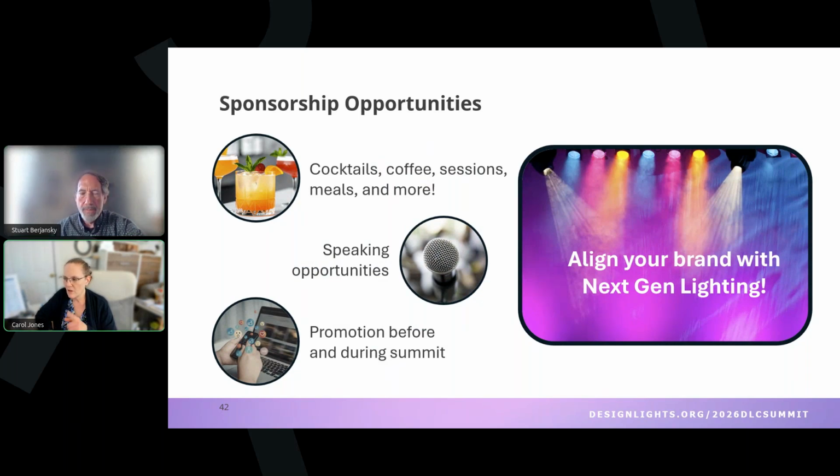Yeah. Another thought that just came up from what you said, Stuart, is that the drivers are all DALI 2 drivers, and there's not much different between D4i and DALI 2. It will depend on things like, are you going to have color? Do you want emergency? Or do you want it to be intraluminaire? When you are using wired systems versus planning to use it with a wireless layer, you have to do slightly different configurations in the factory. But it's not really different. It's just more about how you're applying it, whether it's inside of a luminaire or whether it's part of a more connected system with wires.